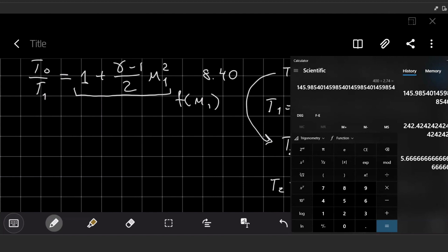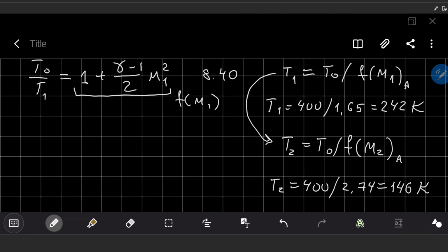Becomes cold. But we are losing the potential energy of the flow, and we are transforming this potential energy to the kinetic energy of the flow. So Mach number rises and temperature, unfortunately, goes down. So it's quite cold, but a very high velocity flow. So we have this temperature at point 2, and now I will make a transition from point 2 to point 3 through my shock wave, through my normal shock wave.